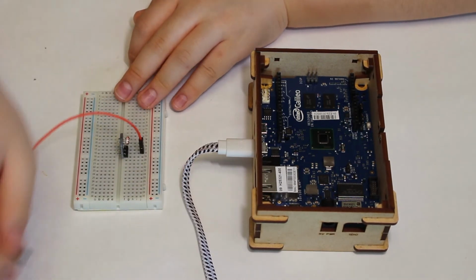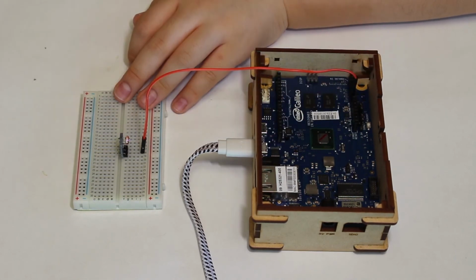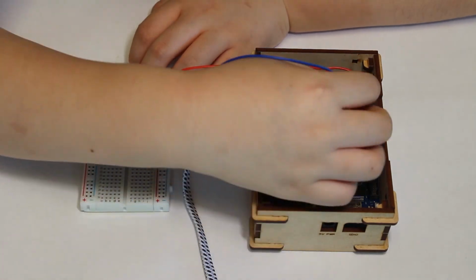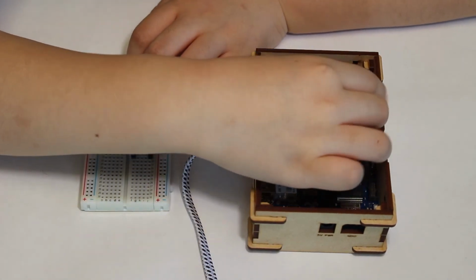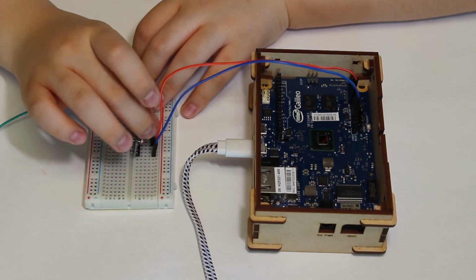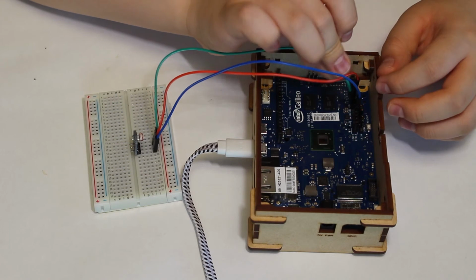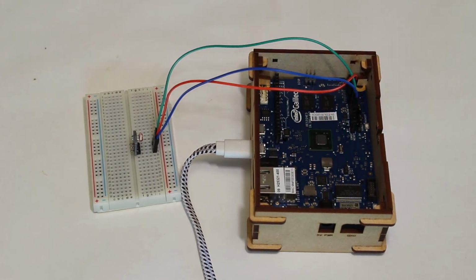Connect the jumper wires to VCC and GND of the light sensor with the Galileo's 5-volt pin and GND pin respectively. The jumper wire of Galileo's A0 pin should be connected to the OUT pin of the light sensor. There is no source code for this experiment in the IDE's examples, so you need to download the lightsensor.ino file from the homepage.